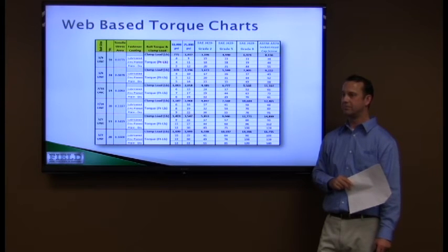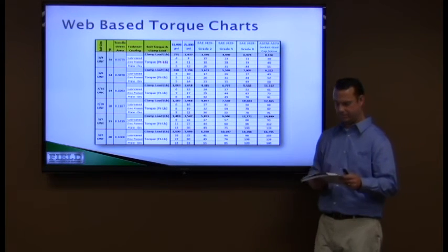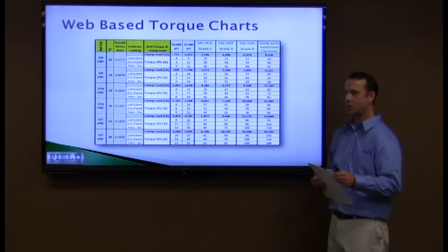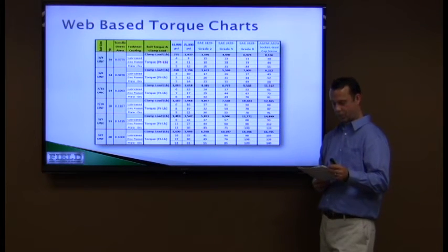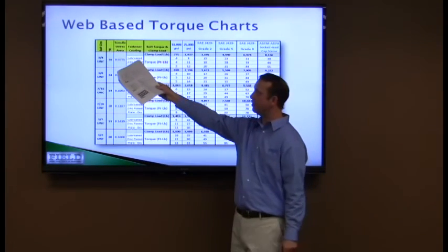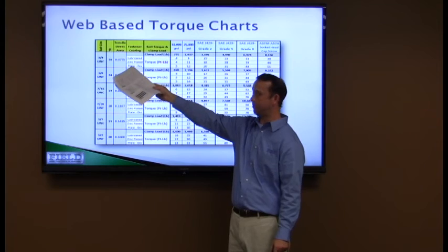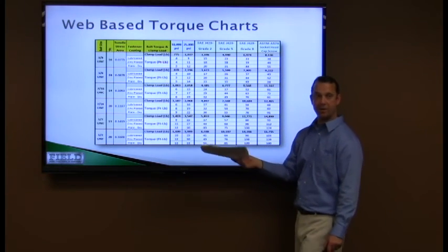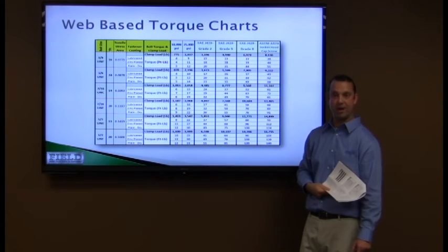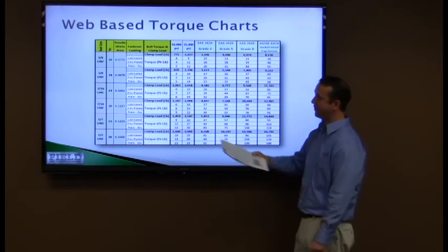Nathan, any idea? Looks better, it's got a lot more information on it. I can see lubricated, zinc plated, so they're identifying what finish it is. I'd say it's good. It's a little better. In general, they've actually specified between lubricated, zinc, and plain. But again, the problem is they don't mention geometry, they don't mention head diameter. If you've got a part with a serrated bearing surface, this won't help you very much.